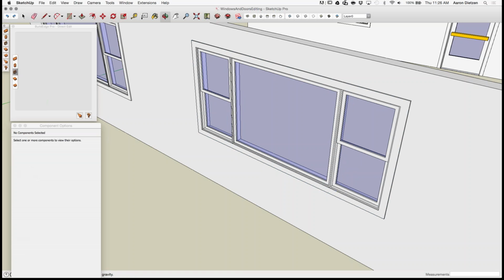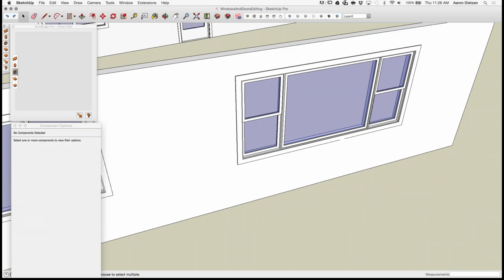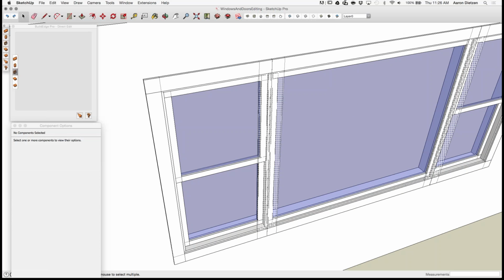By doing that, because of the way that trim is placed, the edges are hidden. Actually, let's go look at hidden geometry. Well, that shows a lot more than I wanted to see because this geometry is still here. But you can see the way the trim is broken up. The trim is actually 8 pieces, 3 across the top, 3 across the bottom, and 2 in the middle. But those controls are hooked up in such a way that turning that invisible actually turns all those pieces off and leaves the 2 hidden ends butting up against each other.